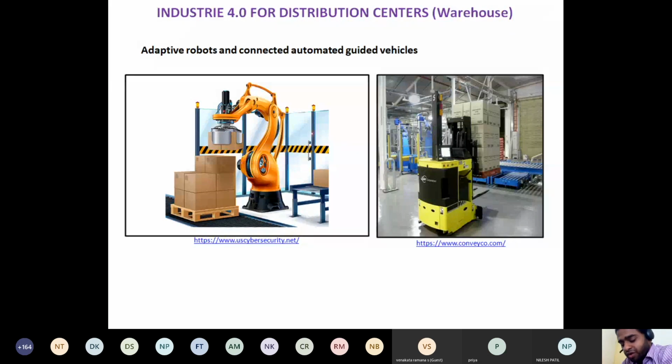Amazon Robotics, formerly Kiva Systems, has designed robots to move racks irrespective of product size and shape of objects within the racks. The robots, called pods, are controlled by a centralized computer using a secured Wi-Fi network for communication. They use infrared technology for obstacle detection and floor cameras to read QR codes on the ground to determine their location and direction. The key to the robotic warehouse's success is not the robot, but the brain behind the system.